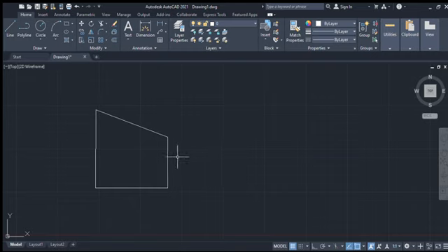Now, if I want to mirror this, I can decide to mirror it at a distance of 100 mm. So to do that, I will have to offset the side by 50, sorry, by 50. So I can decide to offset this by 50, put it to the right of the object, I place it there.